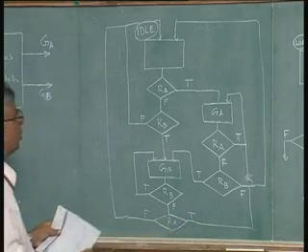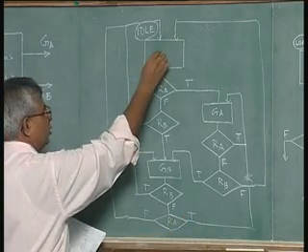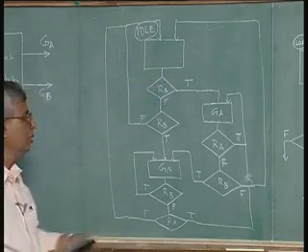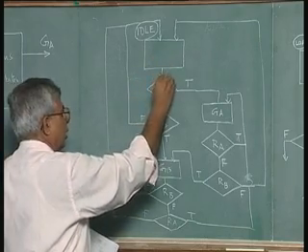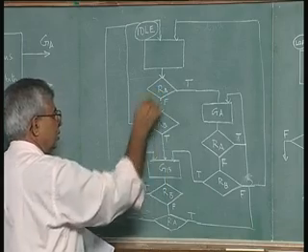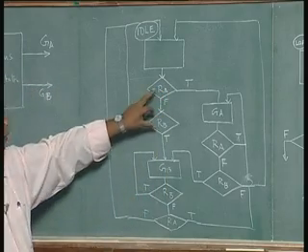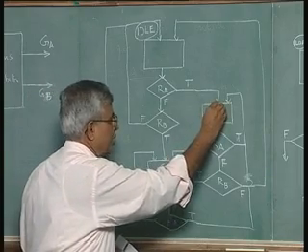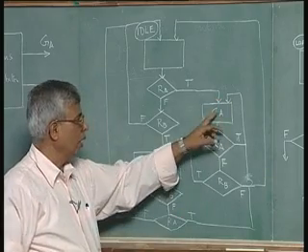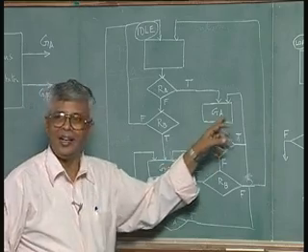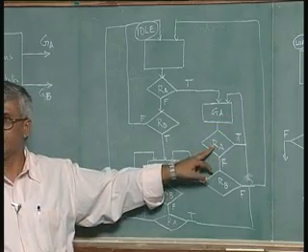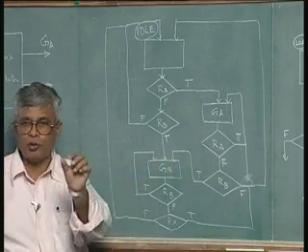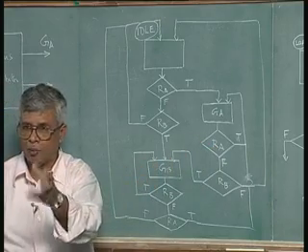So, this ASM is very simple. There is an idle state, there is no output inside, I have not put any output in the box, and you keep checking RA and RB in the same clock cycle. If RA is true, the next clock cycle you issue GA, and keep issuing GA as long as RA is kept high. That is the point here, and that is why I put one more RA here. Because I do not want to issue it for just one clock cycle when the request has not been removed.